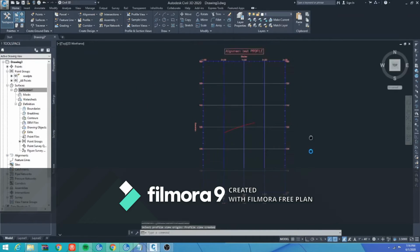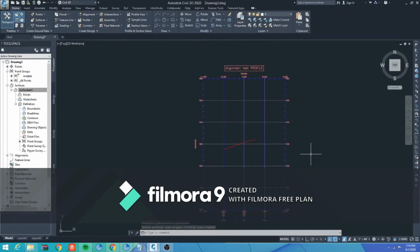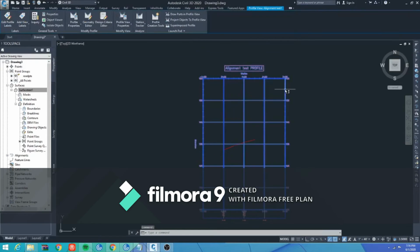So here is our profile. Right now our profile looks a little bit stretched and not in the orientation that we would like. We can always change it by clicking on our profile, and on the top hand corner we can go to Profile View Properties, and edit Profile View Style.